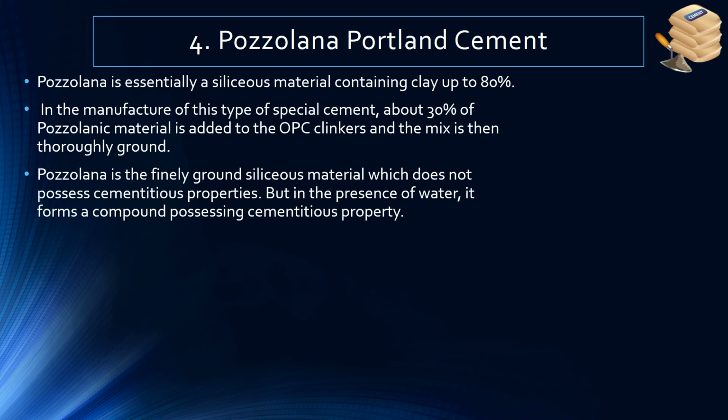Pozzolana is a finely ground siliceous material which does not possess cementitious properties, but in the presence of water it forms a compound possessing cementitious properties. Pozzolanic material does not possess binding property, but when it comes in contact with water, CSH gel forms and possesses cementing property.